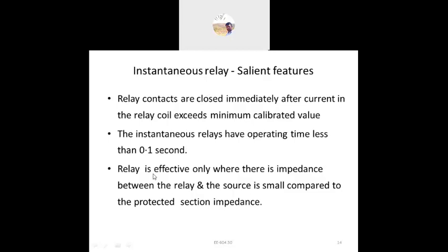Next, the relay is effective only where the impedance between the relay and the source is small compared to the protected section impedance. The contacts will be closed immediately, and the time is less than 0.1 second.